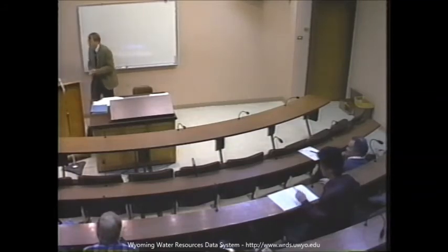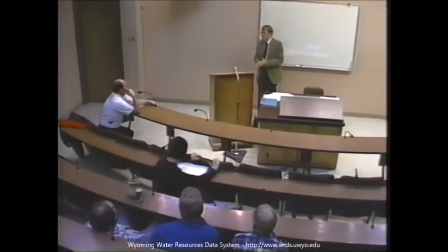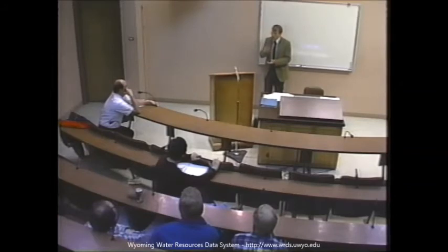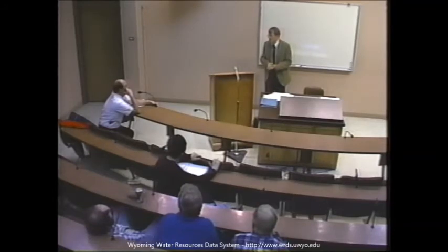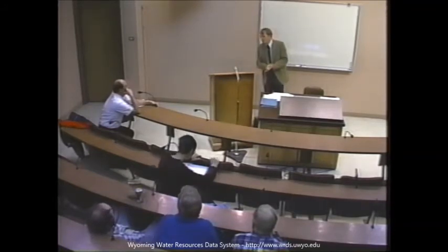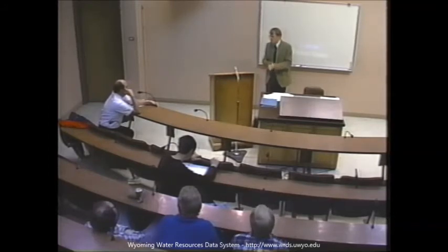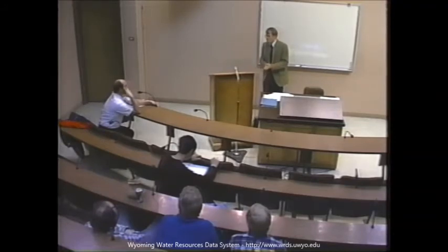Yes. I have a question in regard to when you talk about multiple aquifers, are you talking about aquifers with different transmissivity or conductivity properties? Right, and there might be an impervious layer in between them. Although if we get the partially penetrating case down, we might even be able to handle the leakage between aquifers. Okay. Then I want to take that a little bit further. In your solution set, can you allow the head to vary between layers? Do you have to define that?